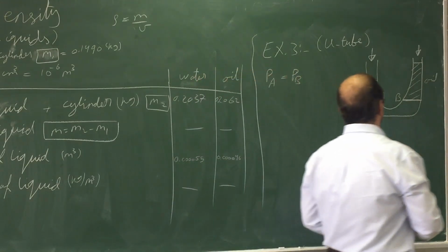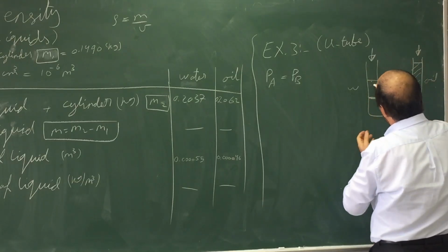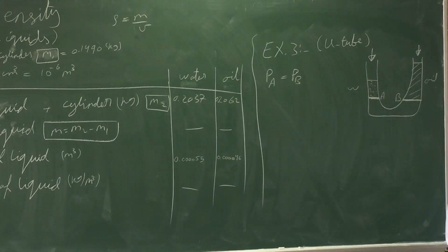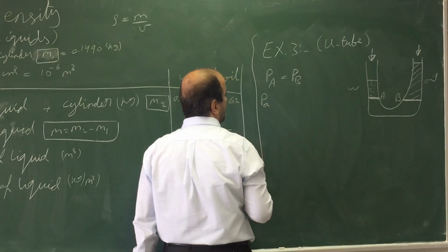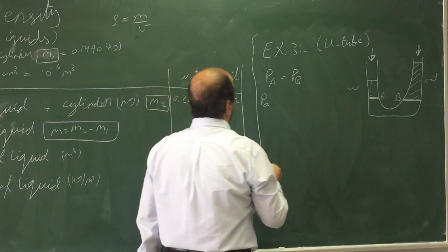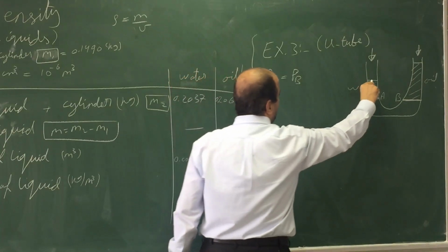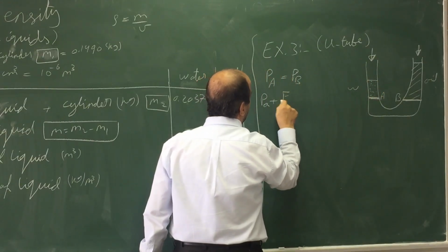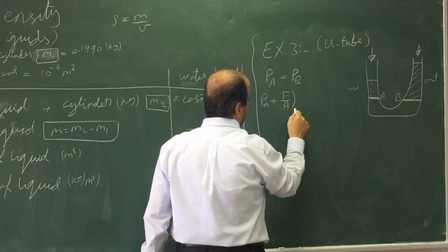The pressure at point A comes from the air column to infinity plus the amount of the water between this point and the surface of the water. This equals the ambient pressure, which equals 1 multiplied by 10 to the power 5, plus the pressure from the water at this point, which equals the force over the area, because pressure always equals force divided by area.